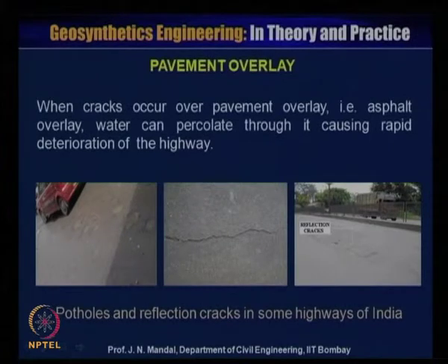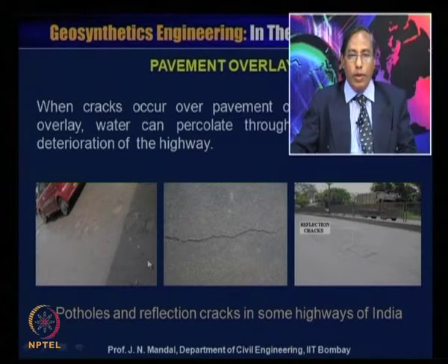Now, pavement overlay. When a crack occurs over the pavement overlay, that is the asphalt overlay, water can percolate through it, causing rapid deterioration of the highway or roadway. You can see the road where there is a pothole, there is reflection cracking in some of the highways of India. You can see this may be longitudinal cracking, sometimes you can also see alligator cracking and different types of potholes.